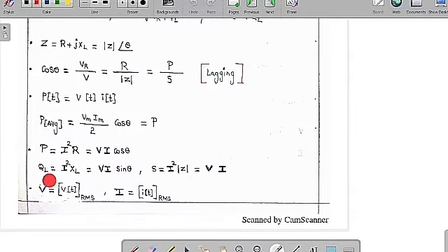And also here QL is equal to I square XL. So we call this the reactive power consumed by the inductor, which is I square XL, and you can also write it as VI into sin theta. If you want to know the value of S, S is the square root of P square plus QL square. If you do this, we get I square mod Z. So simply we can say I square into mod Z, or also V into I, so Vrms into Irms.